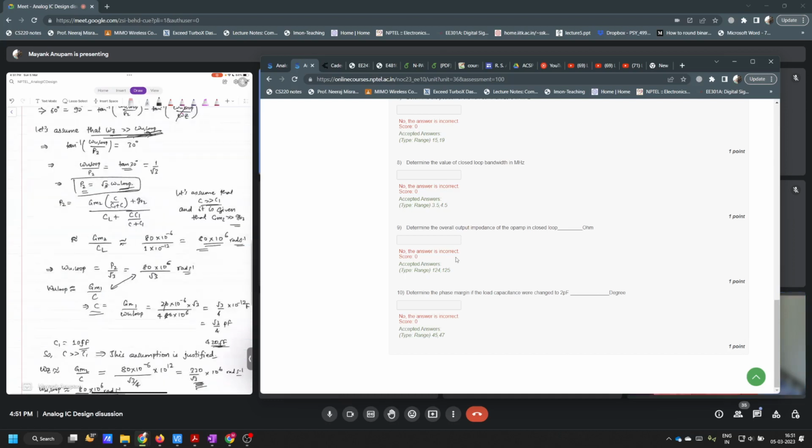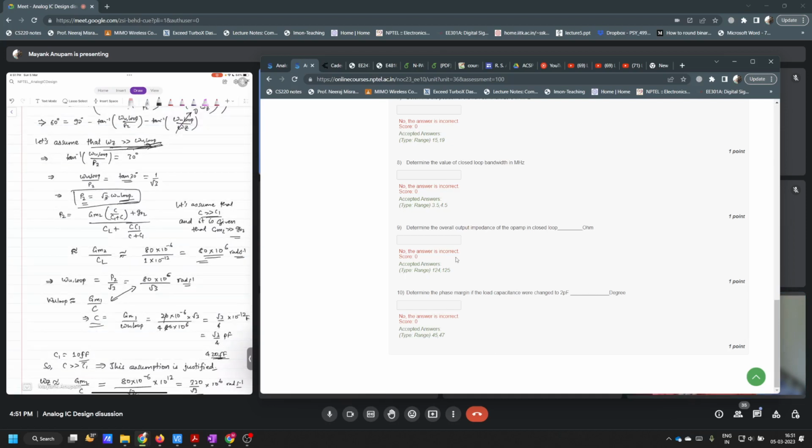But sir, for those approximations we use c much greater than c1. Up to how much? If the value is greater than 10, it's okay. Ten times is good enough. So if it's something like 10 and 200, I can approximate it as 200 only. Yes. If you take a factor of 10, that gives an error of about 10%, which is generally tolerable.